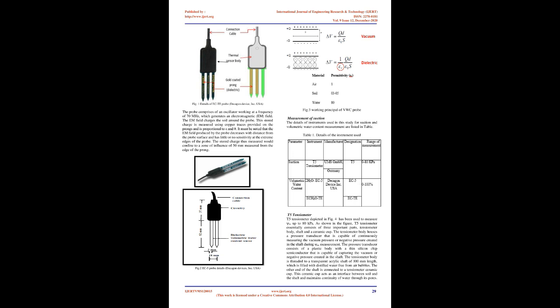The mV output is further converted to volumetric water content based on the calibration equation, Decagon Devices, USA. The value of ε for water is close to 80, for dry soil minerals around 4, and for air it is 1. This means that for highly saturated and dry soil mass, the value of ε would vary between 80 and 4. This broad range of ε is used to determine the water content of a soil mass. Appropriate calibration equation parameters have been used for the geomaterial used in the study by performing laboratory calibration.